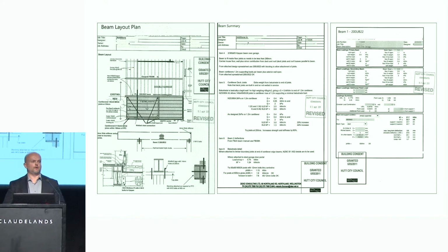So put in your beam layout plan, or how your gravity system is going to be working, and then pretty clearly try to just mark it out, so that when people are going through the beams and so on, they can easily reference across. If your checker can do that, then they can say, okay, well, that makes sense, that makes sense, that makes sense. And if you're looking at it and you can say, okay, well, that's going to need a steel beam there, is that there? That's great.